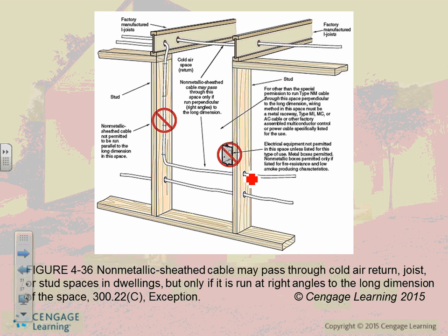The way you know it is by putting a fixture right here, you see a vent, and you look above it, and there are no ducts. It's just a little vent at the bottom. This means they're using the cavity as a return.